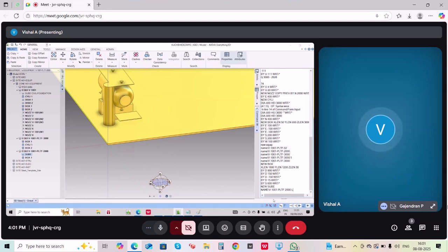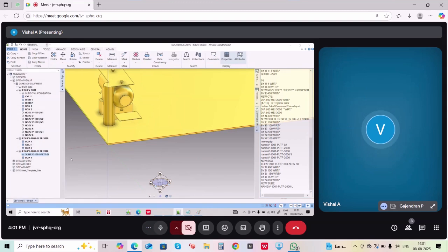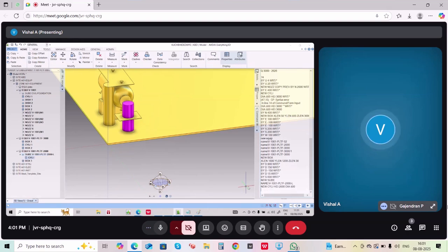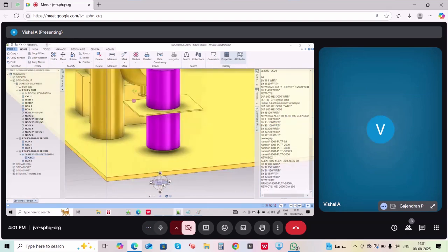L means for ladder, S for stairs. So this is your sub equipment, and inside this sub equipment you can create a new box and cylinder. You got my point? So you have to create a new cylinder, and the height will be like, for example, 2000. Dia will always be 800, and then enter. Oh, 2 by 2000. Sorry, not 2000.